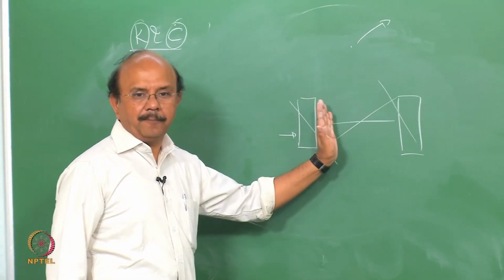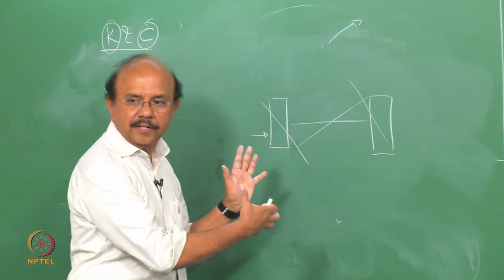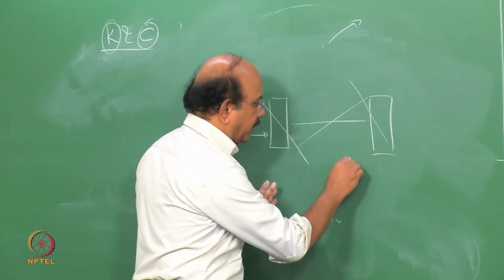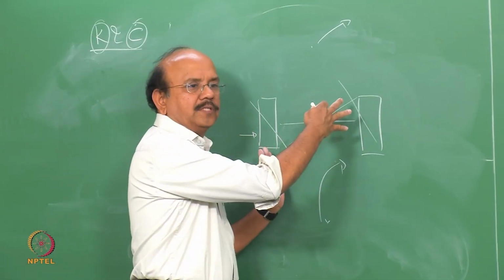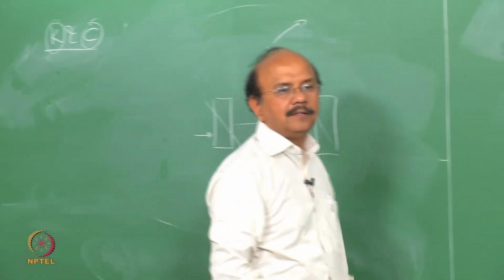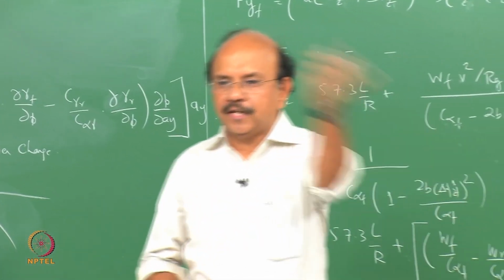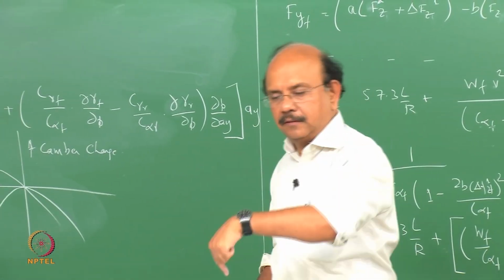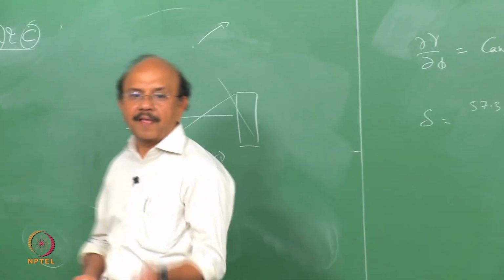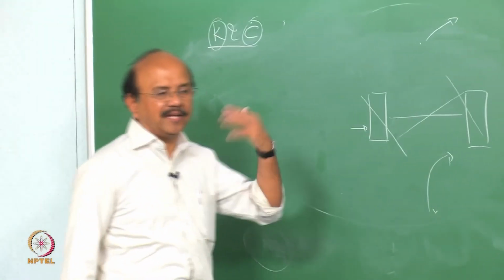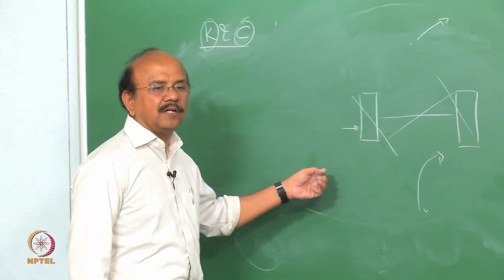If this happens to be the front and the yaw happens to be at the rear, and if you're going to now take a turn like that and your wheels are now towards the left, then you have to give more steering in order to steer that back, and so you would cause understeer. Remember, delta increases, understeer increases. This is due to lateral compliance steer.